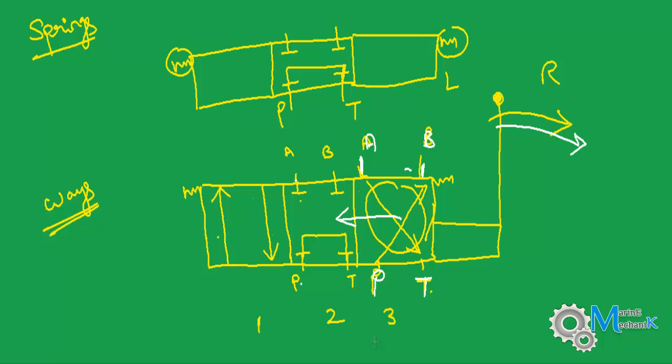So the high pressure fluid from the pump goes through this direction, through this arrow, goes to port B. So these are the passages through which the oil or fluid passes to B, and then there might be some piston or motor. The hydraulic fluid under pressure performs work, and then the return exhaust or drain comes through port A, and this is connected back to tank.